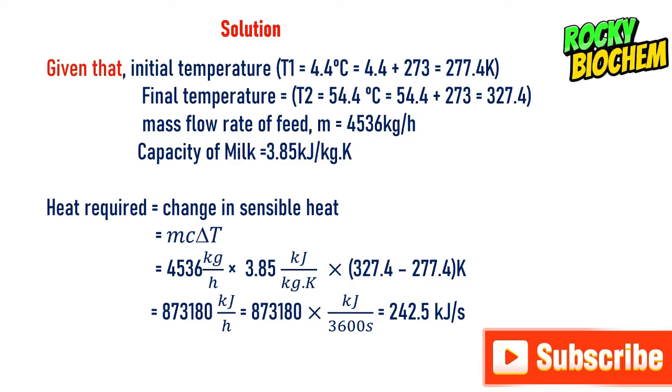And mind you, we have to have our final value in the form of kilojoule per second. So when you have any value and you want to convert it to kilojoule per second, just divide it by 3,600. So when we multiply the whole of these by kilojoule per 3,600 seconds, we are going to get 242.5 kilojoule per second. And 1 kilojoule per second is the same as 1 kilowatt. Hence, our heat required will be equal to 242.5 kilowatts. So this is how the calculation should be performed.